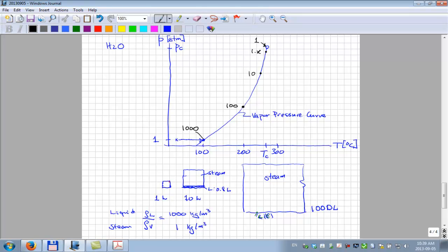Now it's going to be difficult to see because the properties are so similar. The volume change can't be very much, but when you get real close to that, you can change the volume a little bit, and it goes from being all steam to all liquid, and they're so similar in properties you can't probably even see a meniscus between the two, an interface. So the interfacial tension, for example, approaches 0 at that point. Okay? Whereas the interfacial tension down here might be a value of 100.